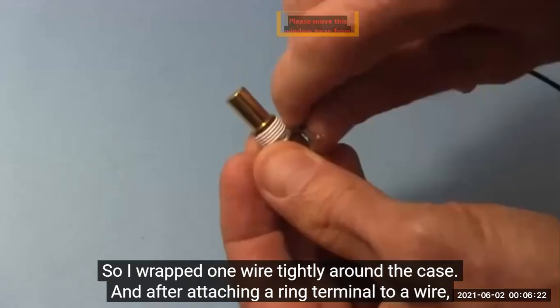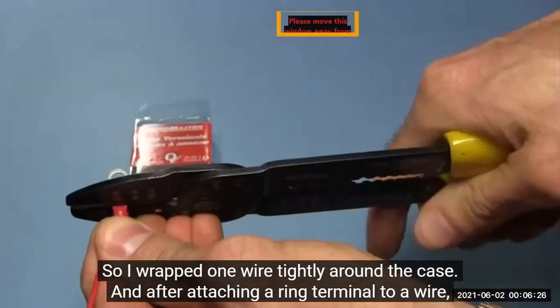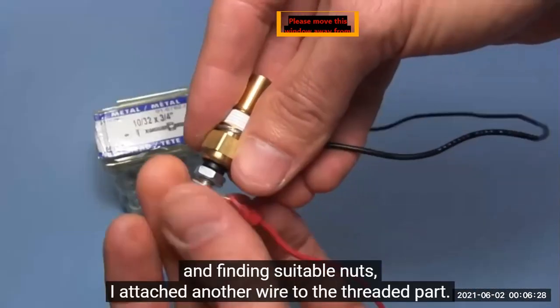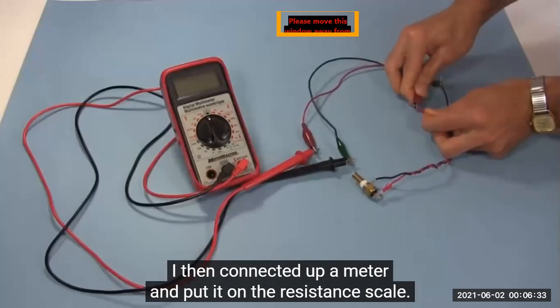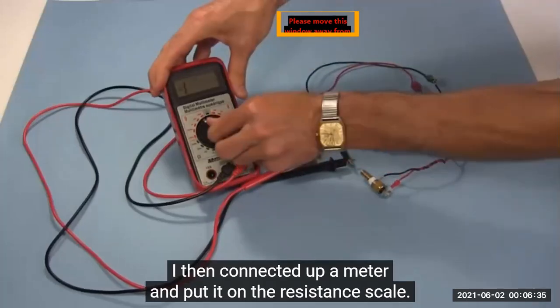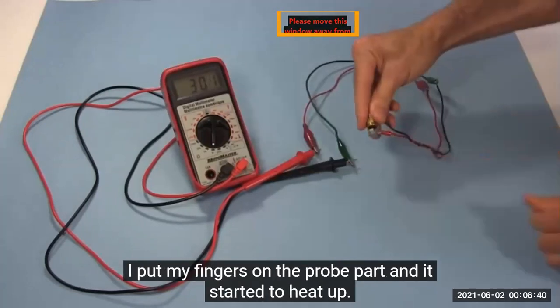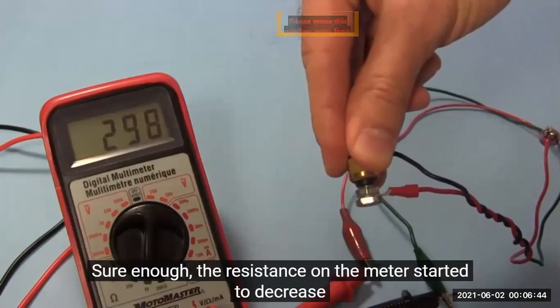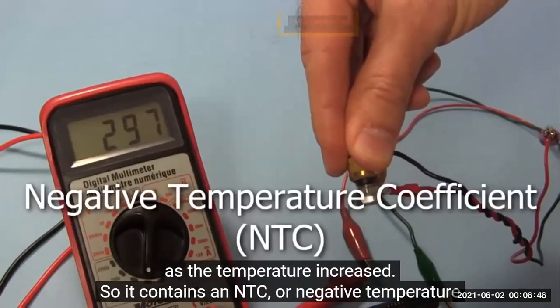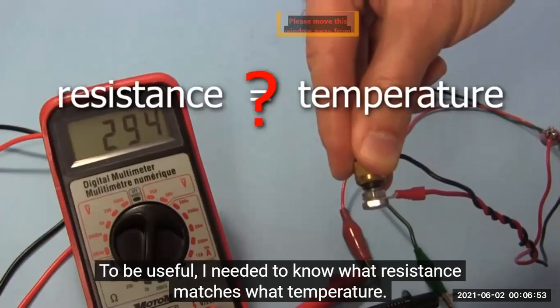So I wrapped one wire tightly around the case, and after attaching a ring terminal to a wire and finding suitable nuts, I attached another wire to the threaded part. I then connected up a meter and put it on the resistance scale. Remember, the resistance changes with the temperature. I put my fingers on the probe part and it started to heat up. Sure enough, the resistance on the meter started to decrease as the temperature increased. So it contains an NTC, or a negative temperature coefficient thermistor. To be useful, I needed to know what resistance matches what temperature.